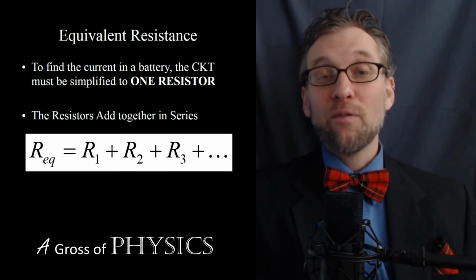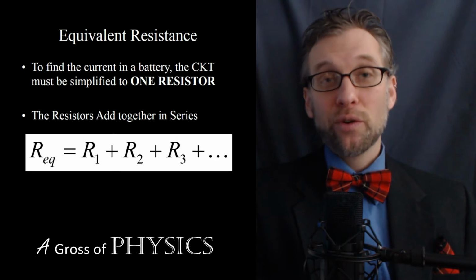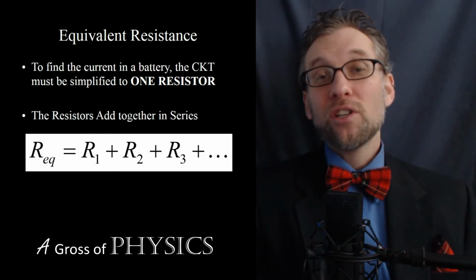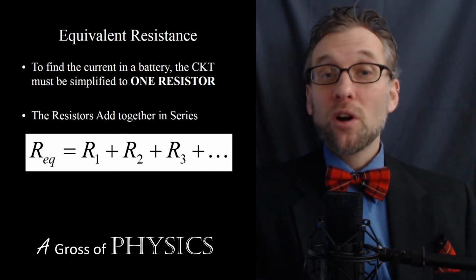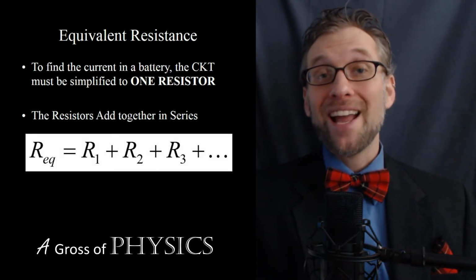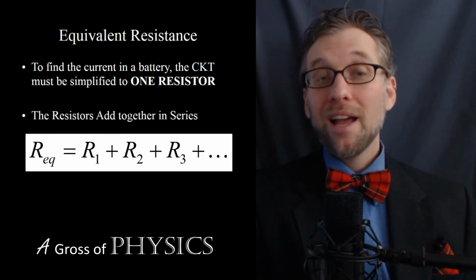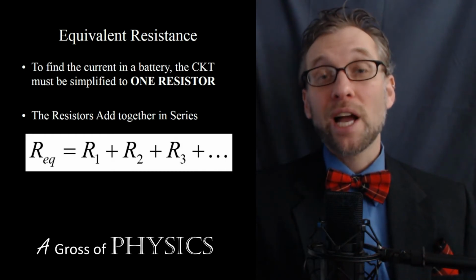And I think the case is if we draw a square or rectangular circuit, you have the battery on one side, and then each of the other 3 parts of the rectangle has a resistor included on it. So just visually pleasing. Now, if you have R1 plus R2 plus R3, that will get you your equivalent resistance. And when you have your equivalent resistance, you can draw that as a single battery or power supply and a single resistor. Now, in that case, you can find the current using V equals IR.